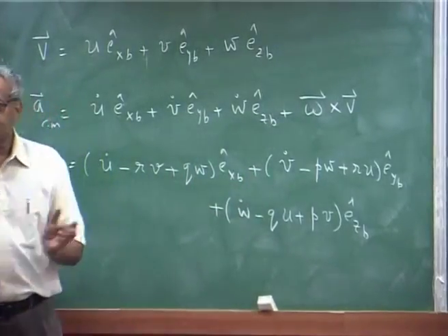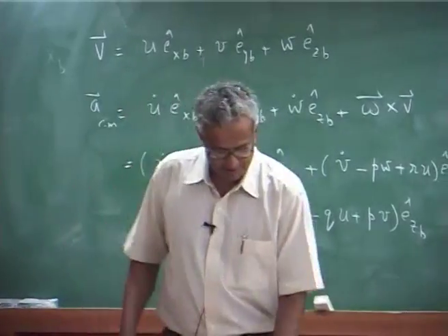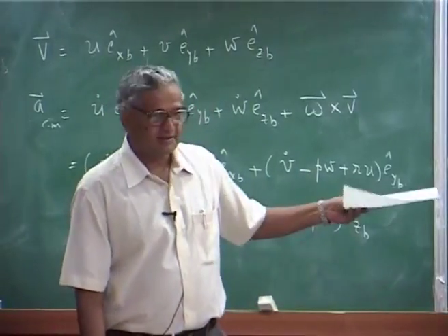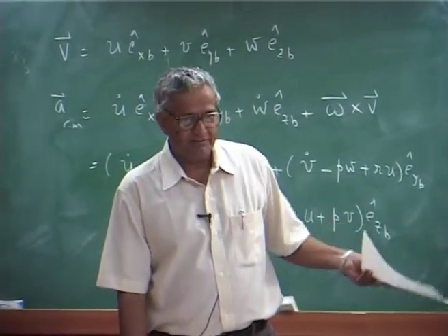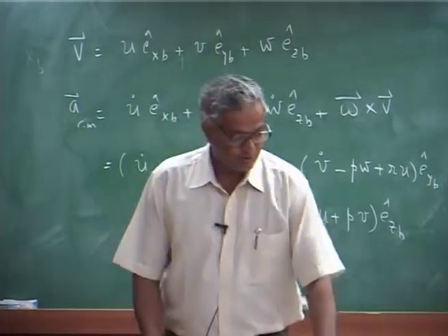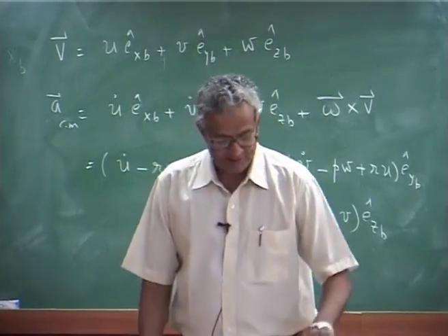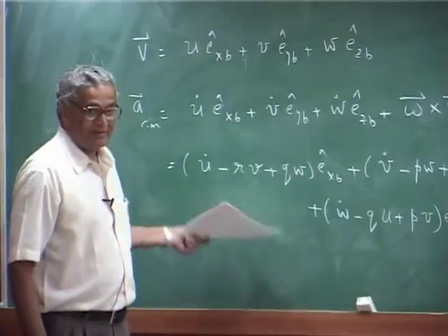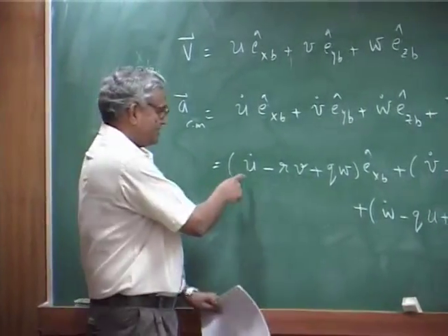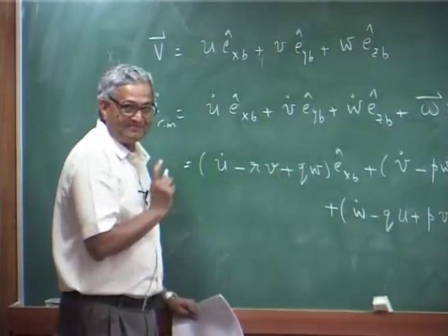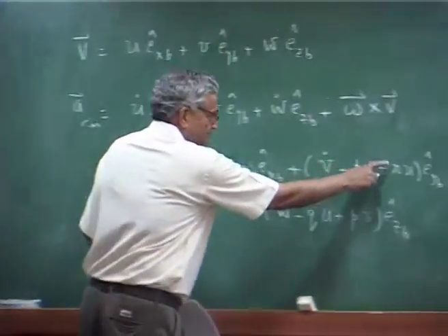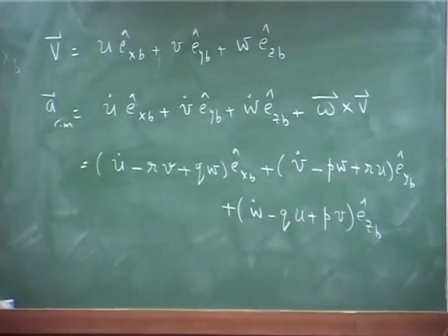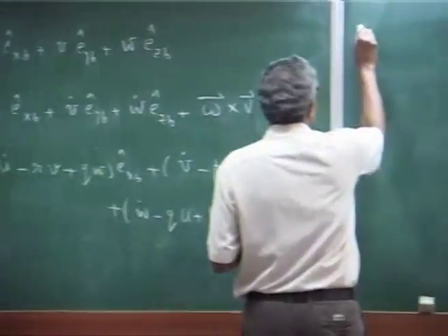So, what are the loads that act on the helicopter? You have a main rotor load, tail rotor load, fuselage aerodynamics, and then any external bodies, aerodynamic surfaces, then gravity, all. So, what you do is you take all the loads and transfer them to the CG. So, you will write Fx equals mass of the helicopter times this. Fy is mass of the helicopter times this, Fz is this. That means you have 3 force equations.